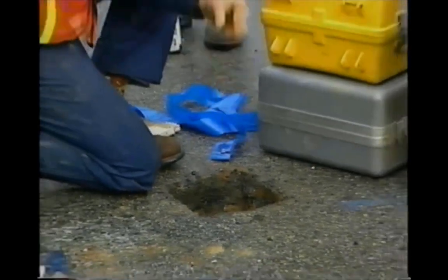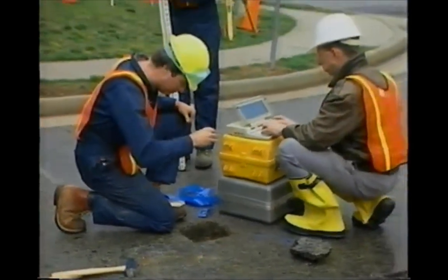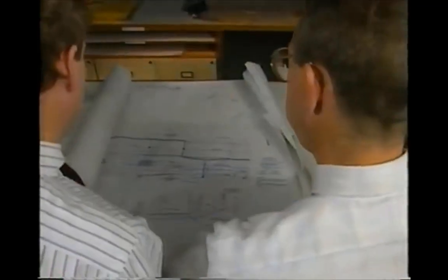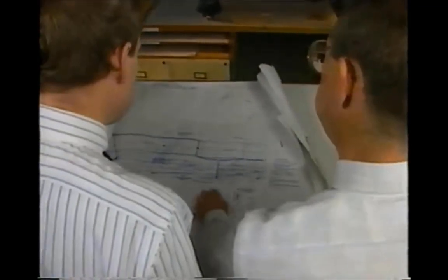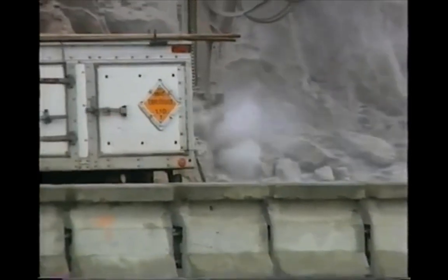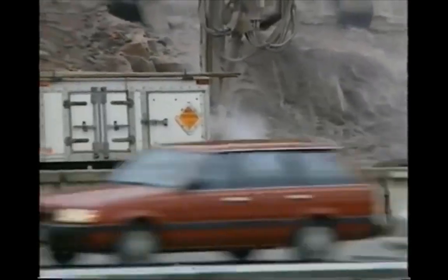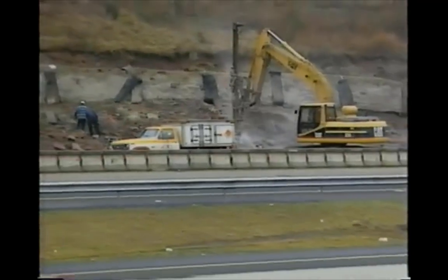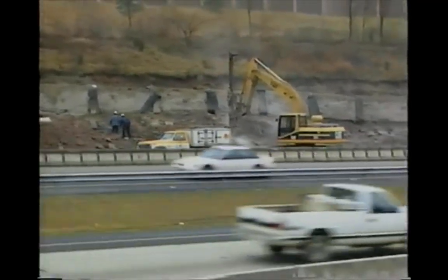Subsurface utility engineering involves the collection of underground utility data and the use of that data by the right parties at the right time. Its major components, designating, locating, surveying and mapping, and data management, can be defined in terms of quality levels of information. Quality levels may be thought of as degrees of risk, or how much information is really needed before planning, designing, and constructing a project. There are 4 quality levels.